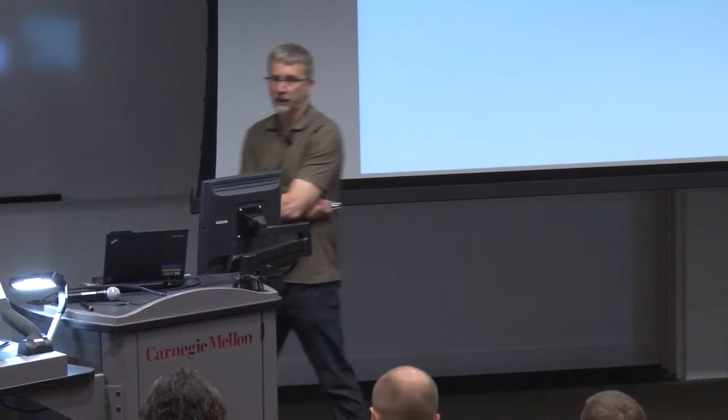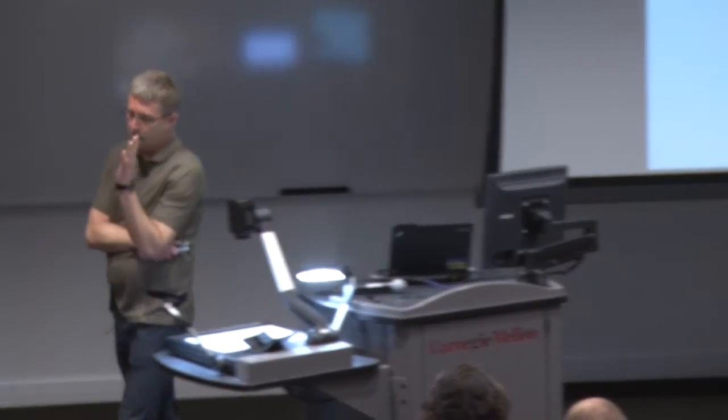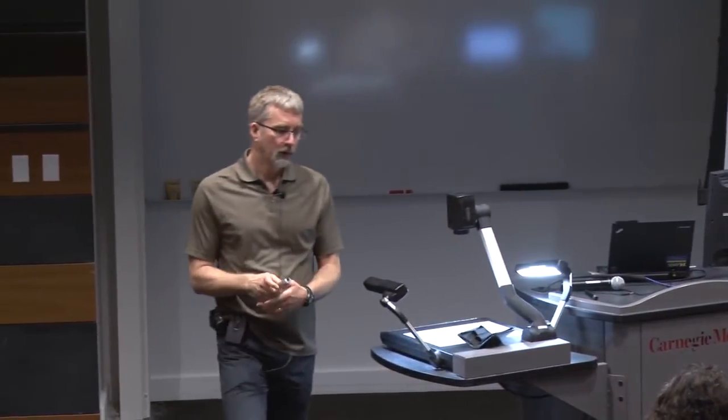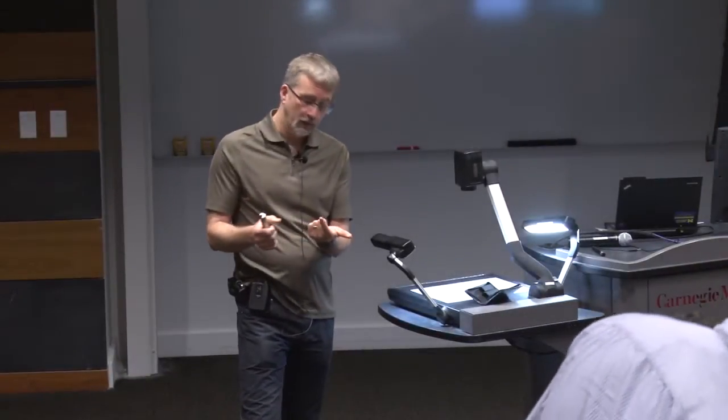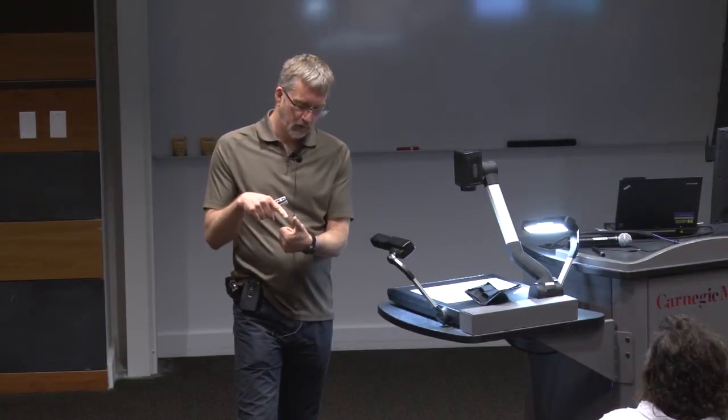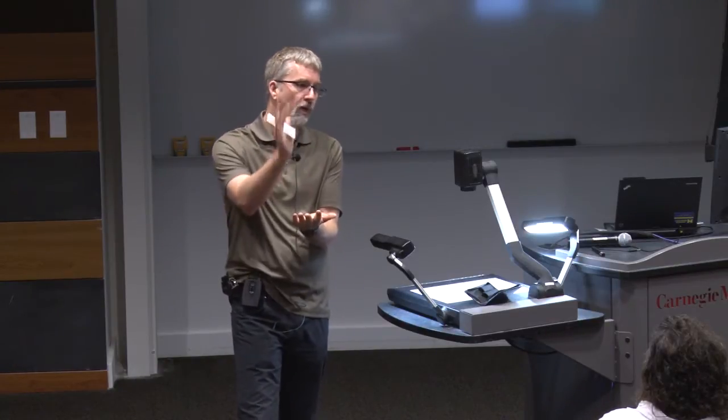Well, why not give what we're doing a shot before we throw it out the window and try something else, I guess would be my answer. For basically sagittal plane motion, if you're either going to synchronize to time or to a phase, as Andy and I have been talking, I'm very comfortable with lots of experimental practice on synchronizing with phase. The roll motion needs to be coupled to what's going on in the sagittal plane anyway, and so that's why I want to do my leg placement adjustment as a function of my mechanical phase variable.